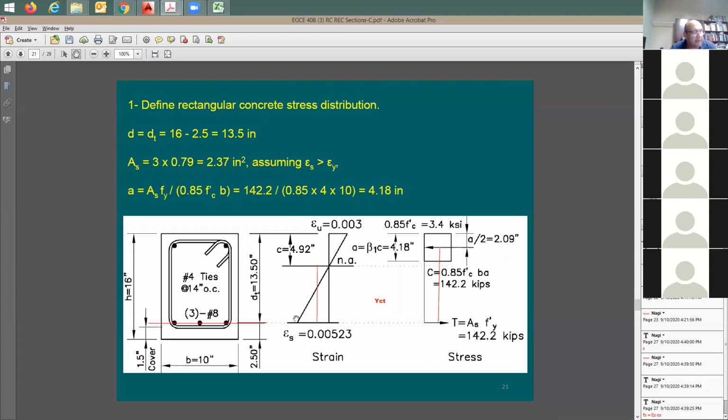Right? So in here, I have section 1, the top of the section, I call it compression. It's going to be tension. This is what I'm expecting when I have moment acting on the beam section. But when I'm receiving here, C value to be greater than D, it means the entire section is going to be in compression. Does it make sense?